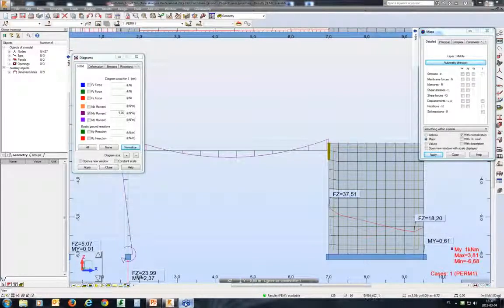Okay, all right, perfect. The next question, which was answered, but I'll read it out loud for anybody that's maybe not looking at the Q&A: do you define a rigid link at the bar end when connecting to a panel? And Francois responded, yes, there's a rigid link to make sure the beam or element is correctly fixed with meshing.